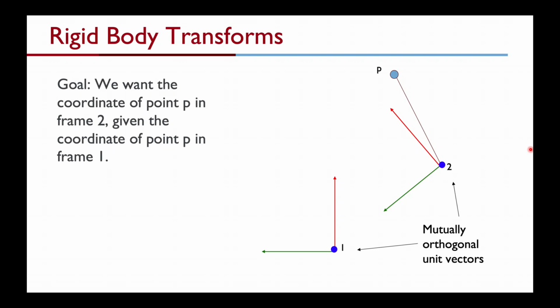And then there are some dynamic transformations where you want to actually compute the position of some obstacle as reported in the LiDAR frame and transform it all the way back to the map frame, right? So it has to go through the base link transform first, and then maybe through ODOM and then to map. So let's look at this thought experiment or a simple example. We have 2 coordinate frames. Right now, it doesn't matter whether this represents a sensor or a base link or the map. This is just a general setup right now.